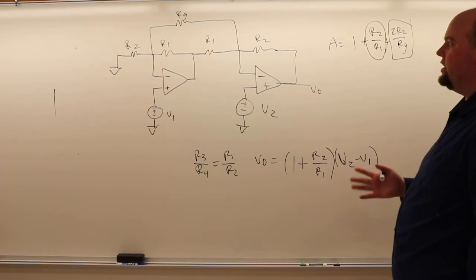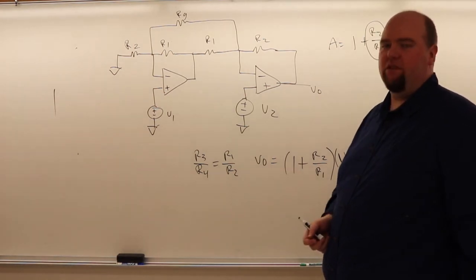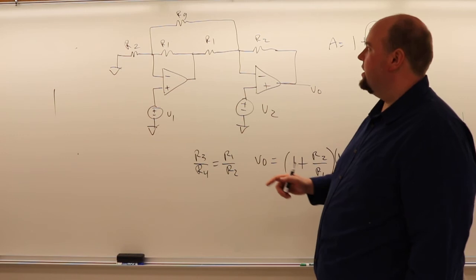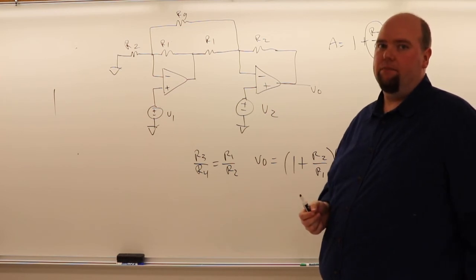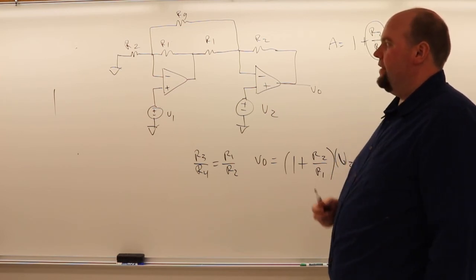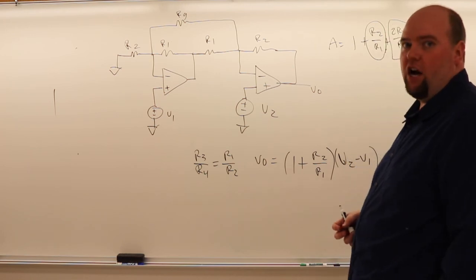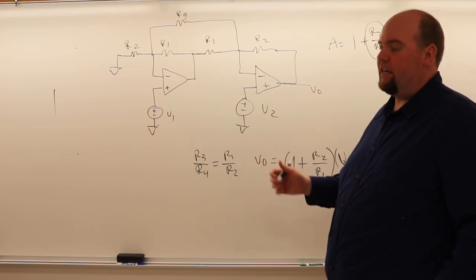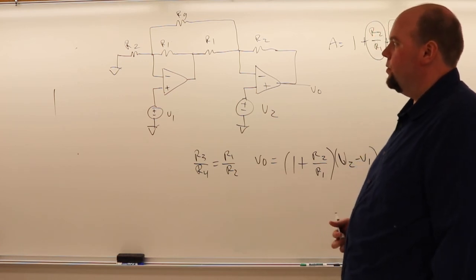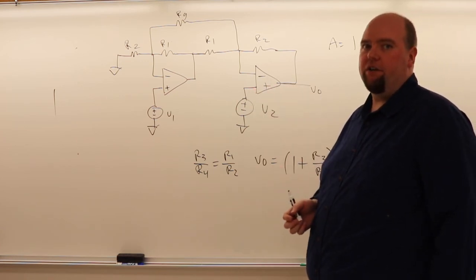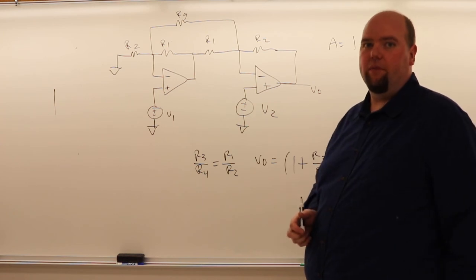So this is just another way to do this, a slightly cheaper way to make a similar performing amplifier. The biggest question is, and we won't do the analysis here, as always, what happens when this ratio slips a little bit? What happens if these resistor ratios start to slip? That is always the question, and that's always the challenge for manufacturers who are making these. How reliably can they guarantee rejection of the common mode in their design? If they can do a better job, they can sell their amplifier for more money. If they can make it more stable over time, they can sell their amplifier for more money. Sometimes that might mean they go to a 3 amplifier configuration. I would say probably 70% of the instrumentation amplifiers on the market, though, are going to use this sort of 2 amplifier connection to do what they do.